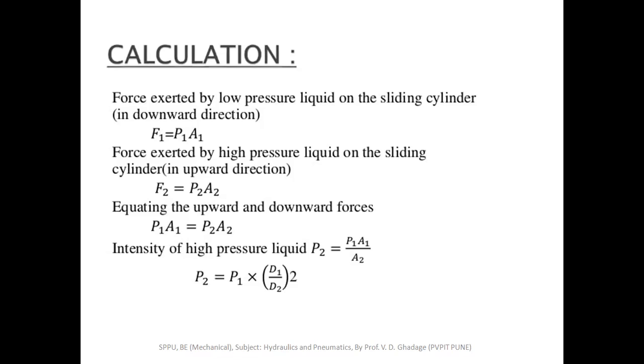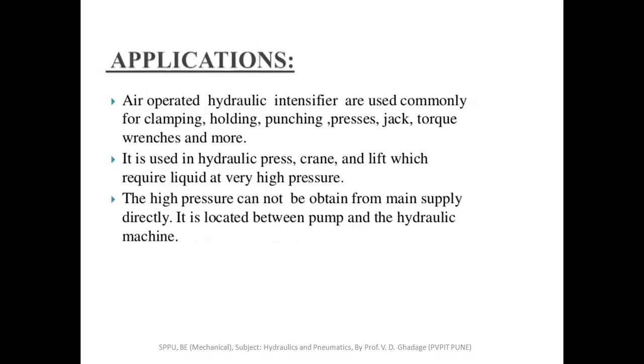Equating the upward and downward forces, P1 A1 equals P2 A2. Intensity of high pressure liquid, P2 equals P1 A1 upon A2. So P2 equals P1 into (D1 by D2) square.